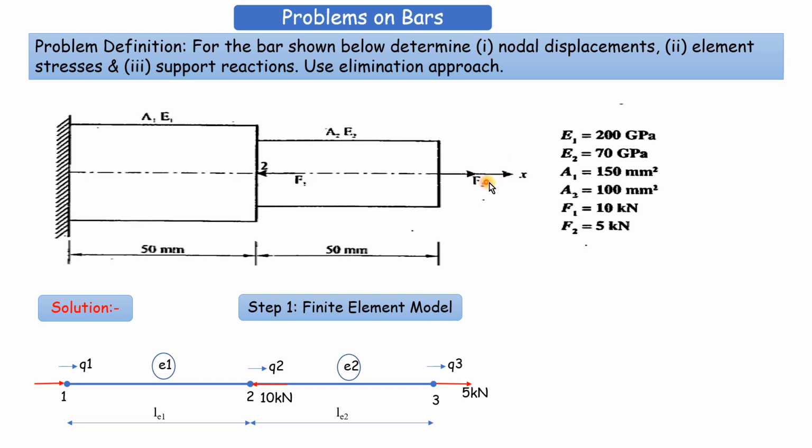So with the help of this, as this is given to you, in that fashion we have to give the node numbers when we draw the FE model of the given bar. So first step is drawing the FE model. That is the first step, that is discretization. So in steps in FEM, what did we study? First is selecting the field variable. So what is the second step? Discretization. So we know what is the field variable here.